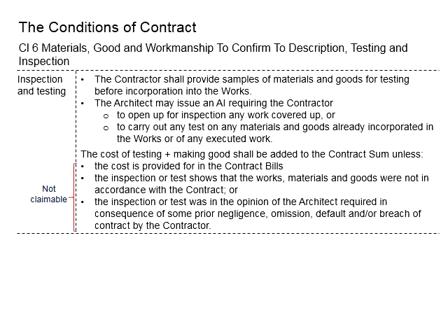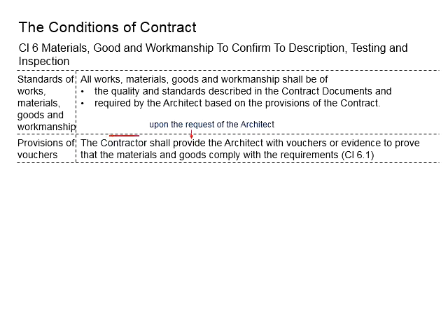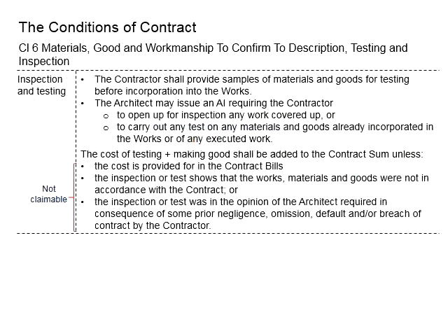That means the architect has the right to request from the contractor. First is the information of the materials to be supplied. Second, the architect may request for samples of the material to be tested before incorporating into the work. Upon request, the contractor will need to supply also. The architect may also request for the testing or inspections even though those materials have already been incorporated into the work. This might lead to the opening up of the works which have already been covered, and the relevant costs for the inspection work and making good of damages that has been made onto the work due to the request for inspections or testing.